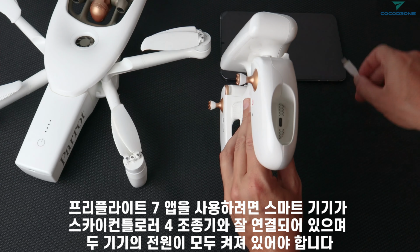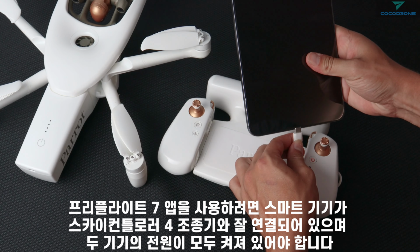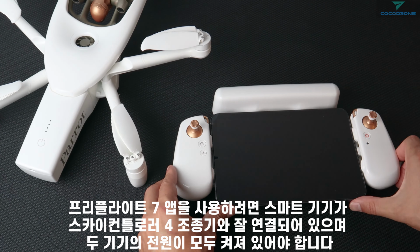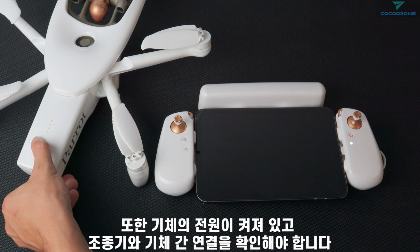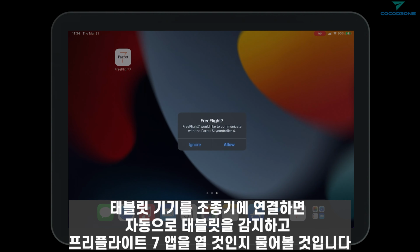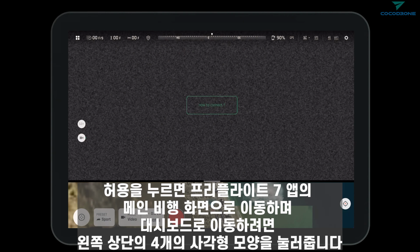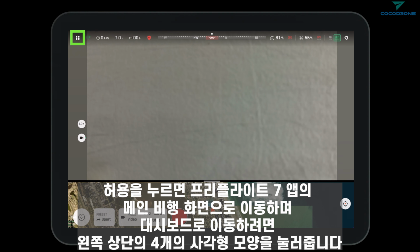To follow along in this Preflight 7 walkthrough, you want to make sure that your smart device is connected to the Sky Controller 4 and they're both powered on. You'll also want to make sure your aircraft is powered on and the system is connected. When you plug your tablet into the Sky Controller 4, it will automatically detect it and ask you if you would like to open Preflight 7. Press Allow. This will bring you to the main fly screen of the Preflight 7 application.